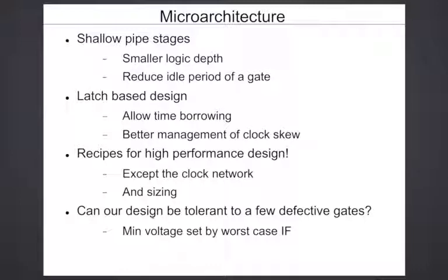For memories, what is done is what is called ECC, error control coding, where you have extra bits in the memory, or you have extra rows and columns. After the chip is manufactured, testing is done, and defective memory cells are identified, and those rows and columns are switched out. That means the circuitry already allows you to ignore those columns and bring in spare columns. Defective columns are disconnected, and you still have a working memory. So that allows you to deal with hard defects.